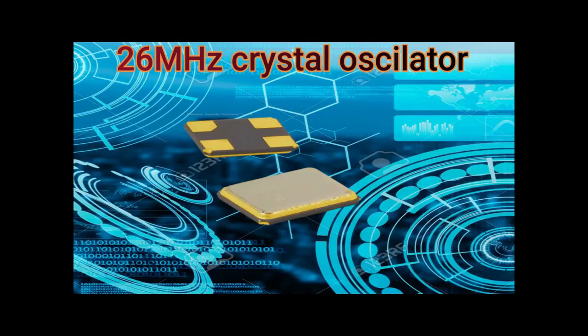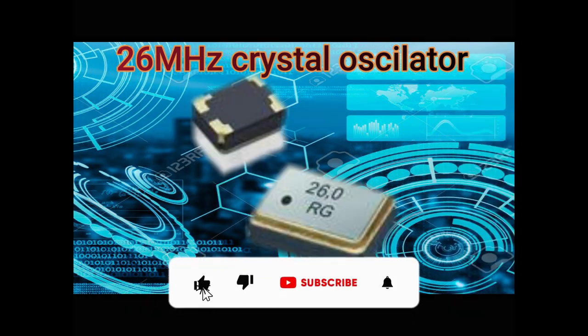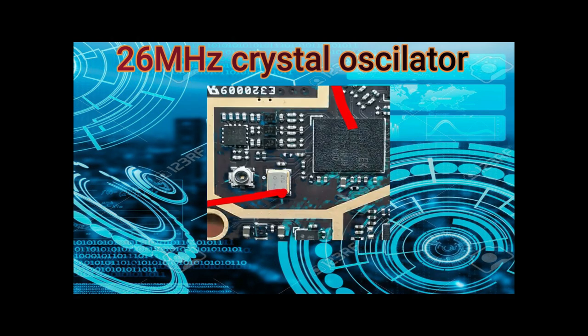26 MHz crystal oscillator. It is also known as the network crystal. This component creates the frequency that makes an outgoing call possible when a user is engaged on the other end. When this component is faulty, one won't be able to make a call and the network also will not be available, and then your phone becomes an MP3 player or iPod. When it is shorted, you can experience a dead phone situation too.